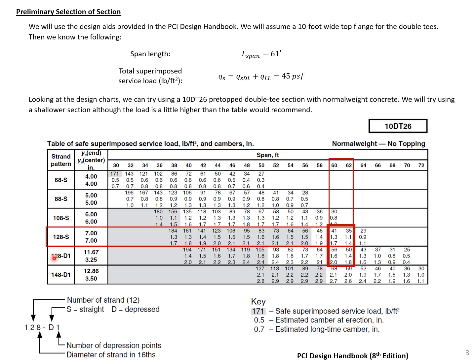So 12 strands, 8 is a 1/2-inch diameter, and the last is whether they're straight or depressed. So the straight strands is saying that we could use a 7-inch height from the bottom to the centroid of the strands. D1, we would have larger eccentricity at midspan. So that'll be the starting point for our design, between the straight strand and depressed strand scenario there.